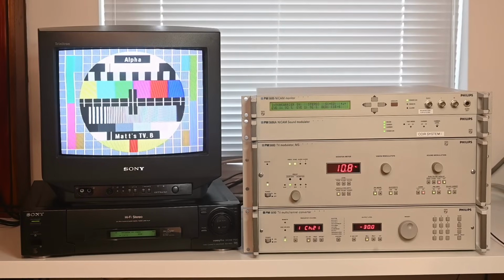So what's happening is that the NICAM decoder in the VCR is losing lock with the source and is having to resynchronize, and while it does that it drops back to the FM mono audio, which is why you hear that sort of change in the sound. Now this might seem like an awful lot of equipment and mucking around to reproduce something that seems fairly trivial, but this was a big deal for stereo sound in the UK, and it did hold things up quite a bit. The solution to the problem here is to add what's called a reframer before the NICAM modulator, and this gives the receivers the semblance of receiving from the same coder, even though in fact it is actually being switched.